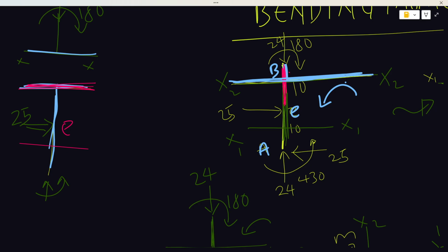So, to get moment at E, which should be done only for moments, I can cut like this, then apply all these things to get an equation, then I'll just plug in the value of x at E. Or, which is what I did, I went through the faster one, I cut here and found the moment at E. This should be done only for moments. If you try it for shear force, you won't get your values.